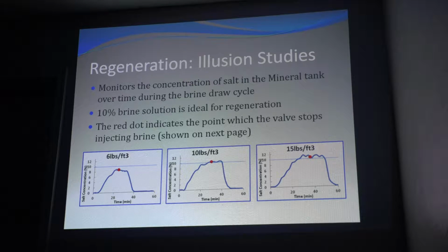So that's why you'll see some water softeners are drawing at 5 gallons a minute. They actually are literally drawing 5 gallons a minute out of the brine tank. And you've got others that might draw an eighth of a gallon a minute. So a lot of times people are like, well, my water softener failed, my injector failed.